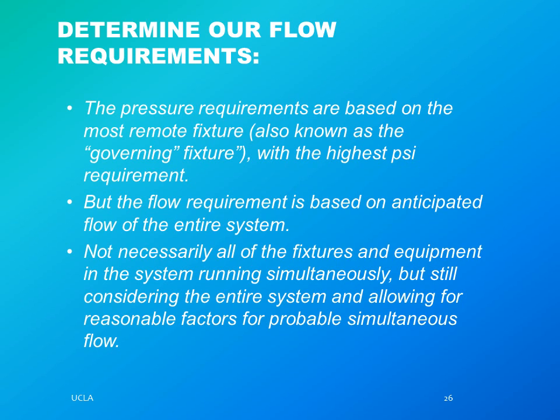But the flow requirement is based on anticipated flow of the entire system. Remember that not necessarily all of the fixtures and equipment in the system are running simultaneously. It's never going to happen, but still considering the entire system and allowing for reasonable factors for probable simultaneous flow. That is what Hunter's curve is about.